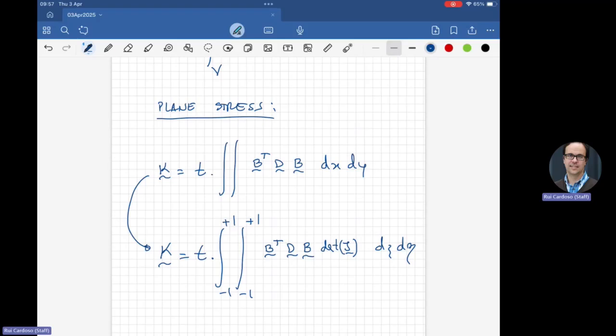Previous weeks we were working with a truss, sort of a strut element, when we introduced the related residuals. Now I'm doing a plane stress element. Okay, just to give you an idea. Now you are in 2D. For the truss element, we only use a one-dimensional shape function, right? Remember? So it was a shape function in one dimension. The strut element had two nodes. Yes. You had two shape functions, 1 and 2, in one direction only, right?